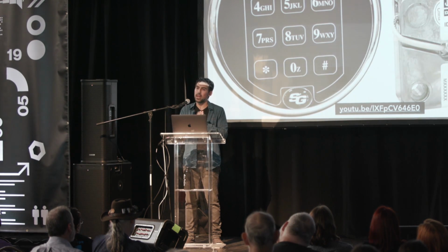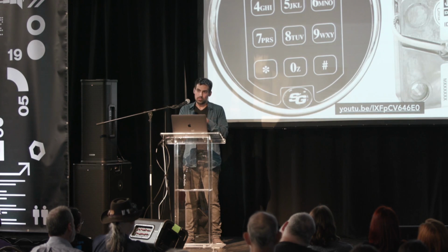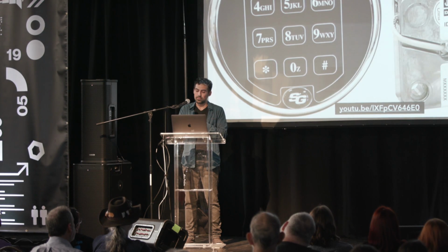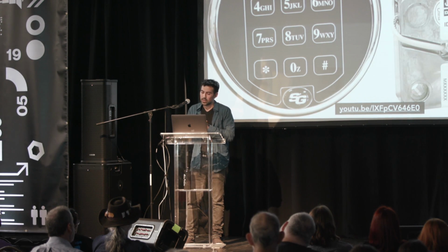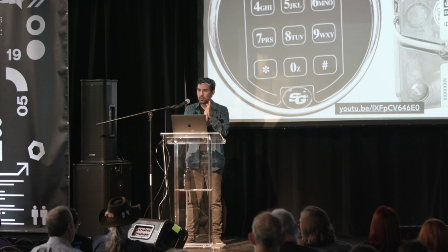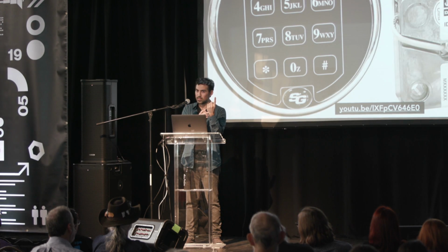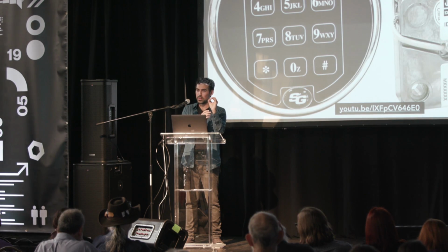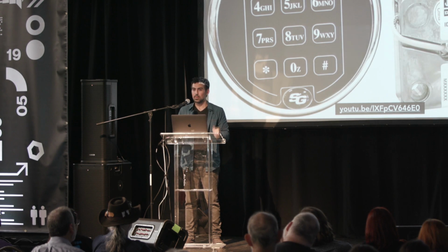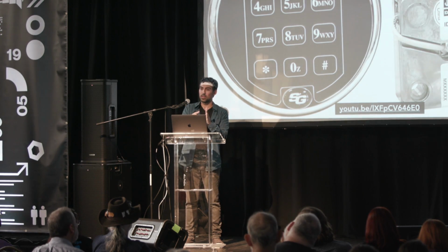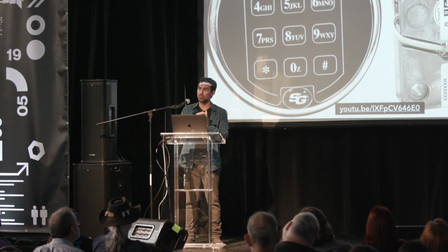If you can time it accurately, and you can, all of this stuff is time dependent, then you wait for the EEPROM to start erasing that 2 to a 0, and then reset. Before it has the chance to program, you've reset that counter and you can perform your attack again. Then you brute force, performing the same side channel attack or timing analysis we did initially, and you've now cracked this UL security listed safe.